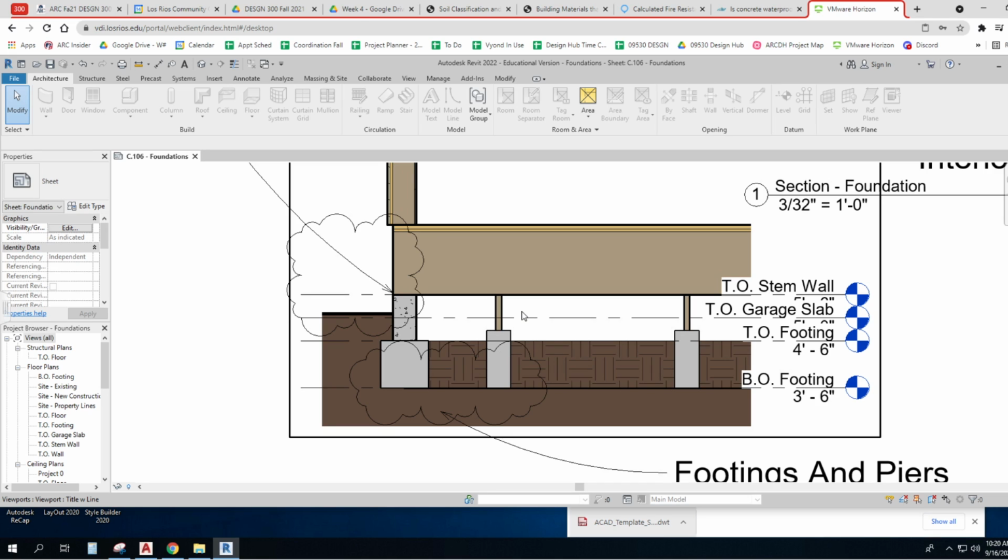But I just bring them up, all of this, the load in between here, any weight that's there has to be supported on these points out here. So depending on how far apart these are, all the load will be taken up over this little spot. And then depending on the wood or the material of this joist, this member that goes all the way across, and depending on how much deflection it can handle or you want to allow it, you'll get some different readings.